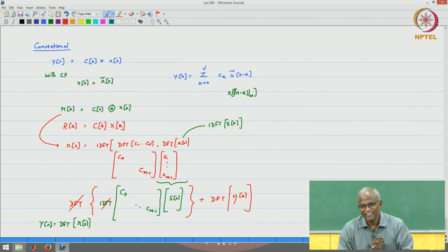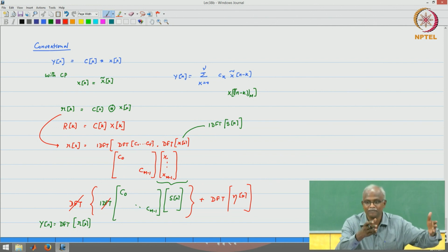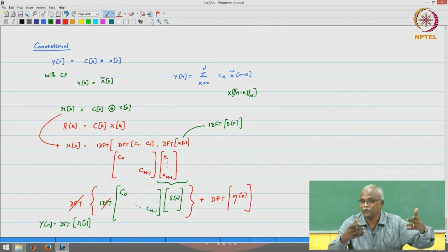I have to defend against that accusation, right. So now you turn around and ask the communications engineer, okay, now what is your spectral leakage? 13 dB, very bad spectral leakage. And where did it actually show up? Remember how many channels I had to put as guard bands in my 802.11. I did what, 6 channels on either side, 12 channels, you have wasted bandwidth.